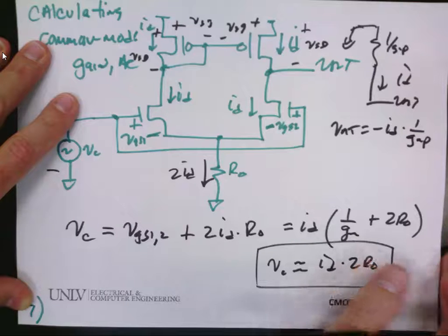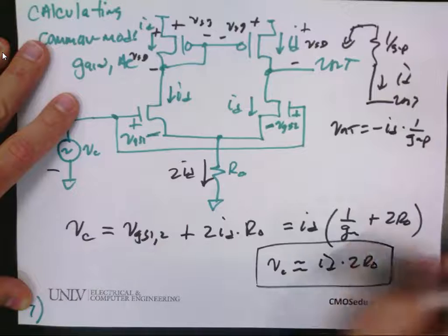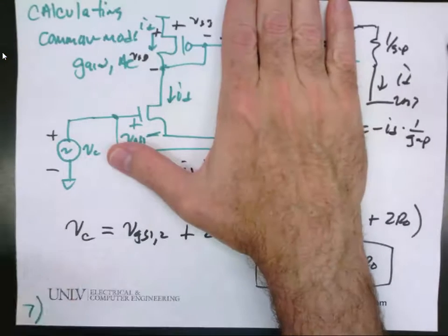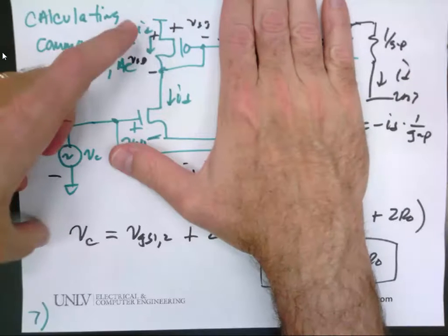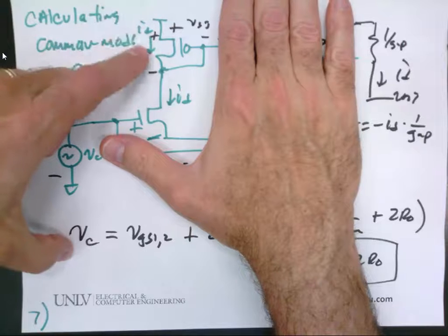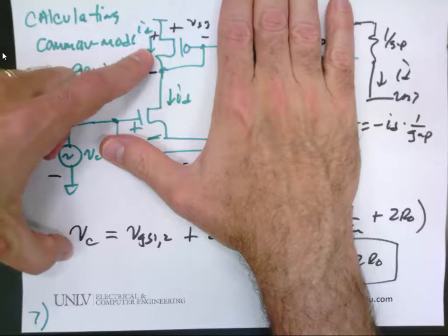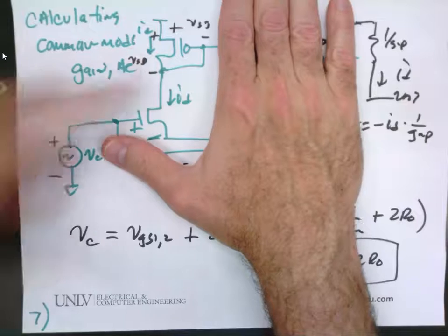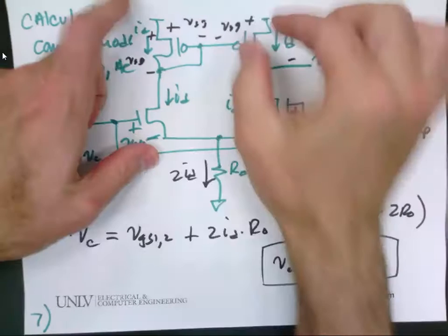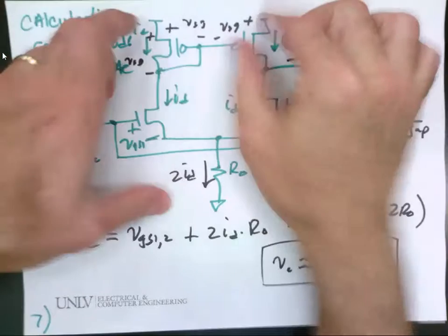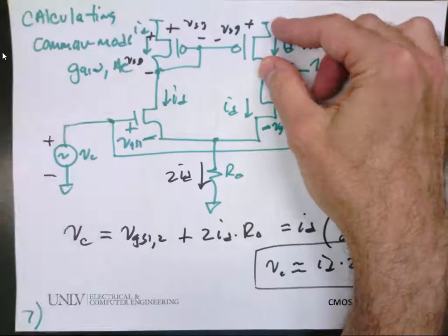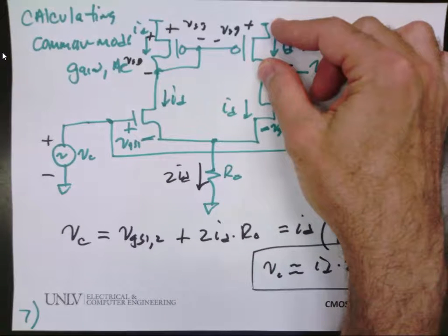Does everybody follow that? No? Let's forget about this part for a second. Does everybody recall, because I went over it numerous times, that a gate-drain connected transistor small signal impedance is 1 over GM. Or if you want to be precise, 1 over GM in parallel with R out, but that's approximately 1 over GM. Right? Everybody agree this VSG and this VSG are the same. This ID and this ID are the same. So if you have the VSG and the IDs are the same, the drain to source voltage.